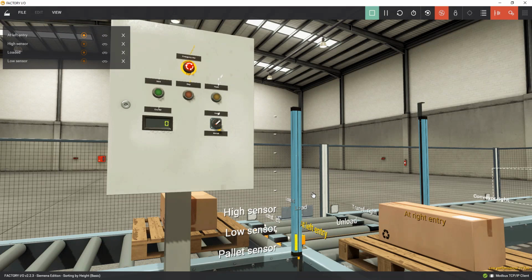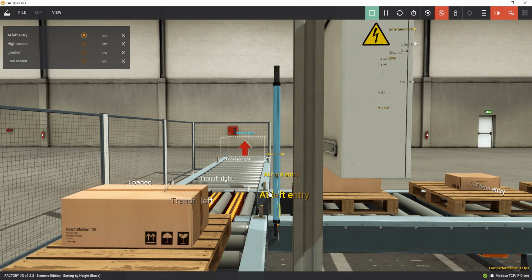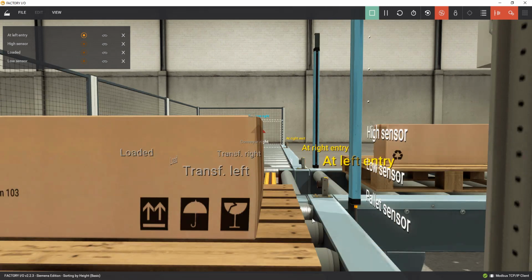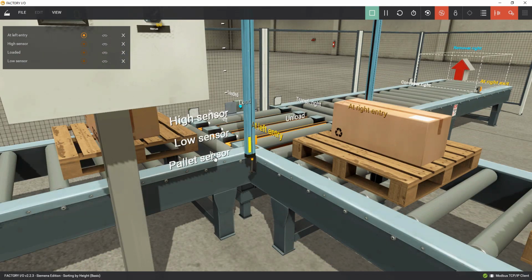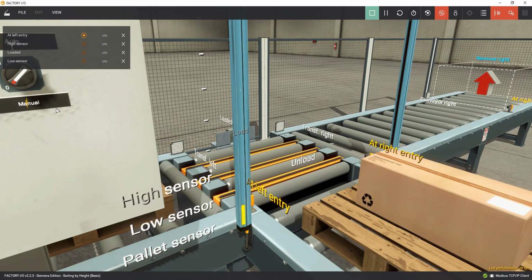So how are we going to restart the process there for the box to go inside? Because like that, basically the process has been completed, so we can't restart it afresh. So what we need now is, let me go to that sensor that I'm talking about. You see the sensor that says entry left, this one, and it's on, it's active. That sensor, immediately when it senses that the box has just passed by, we want it to turn on the conveyor here, and also to stop the chain, because at the right moment the chain won't stop.